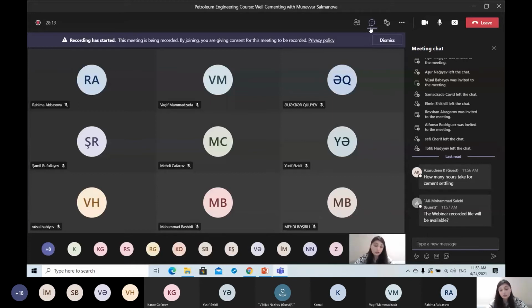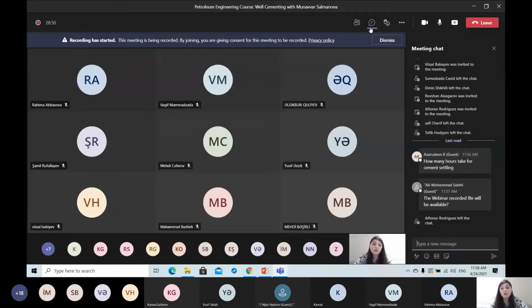We are doing the UCA test, which is the ultrasonic compressive strength analyzer. I will put photos and maybe some videos from our lab in the next sections to show how we did the test. Before the job we analyze it, and mostly we need 500 psi compressive strength to drill, to get solid, hard cement there. This 500 psi is usually reached in around 12 to 24 hours. It really depends on the cement slurry recipe, because we are adding some retarders.